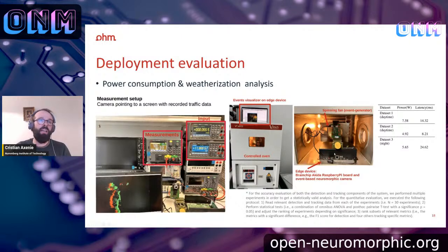But basically, we were also able to measure the power the system got, and I'll give it to you here in the right-hand side table. You have it for the 3 data sets. Instead of having the measurements outside on a gantry, we put a screen in front of the DVS camera, a huge screen, so we were able to replicate the scenario outside. Of course, with the lab lights, one can argue the dynamic range of the DVS is good, but you just demonstrate the lab conditions. One can go beyond, but good luck measuring power with a mobile setup outside on the gantry, which is 8 meters on top of the street.